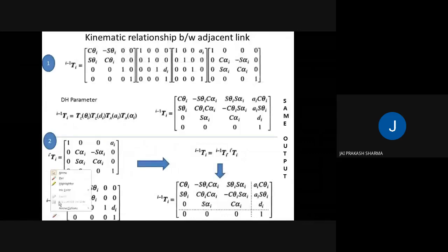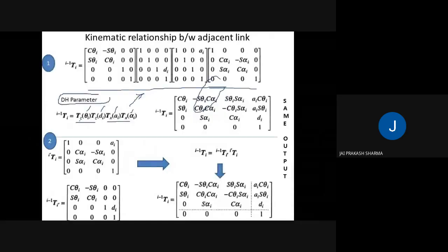The operations which we performed in the earlier slide, that is rotation with translation along the red and green axes, this is about the red axis. So these are the four homogeneous transformation matrices with respect to the transformation we took over here, in terms of DH parameters. What are DH parameters? DH parameters are basically Denavit and Hartenberg parameters. If you multiply these transformations, the final matrix which we got over here is this one.